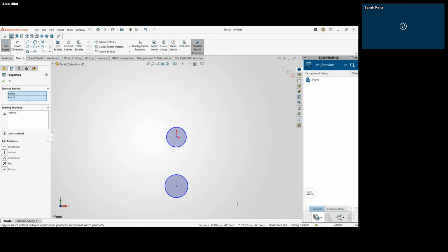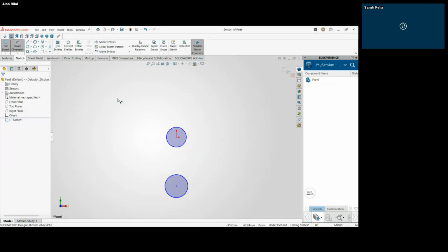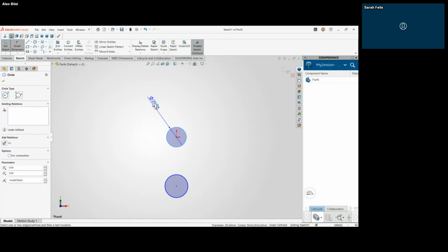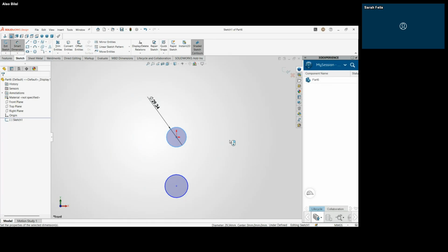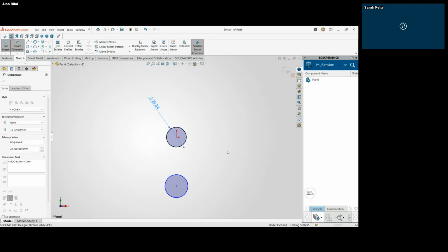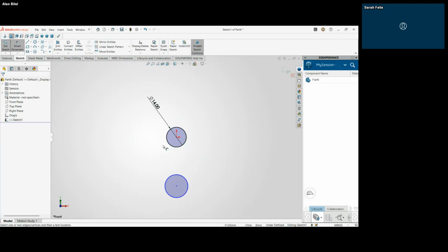So the top one is of radius, no, sorry, of diameter. Okay, no, radius 7, that's diameter 14. Create that. Enter 14. You could actually have used the slot for that. That's using the slot feature so as not to waste too much time. But since we have already used the center circle, we are going to continue.